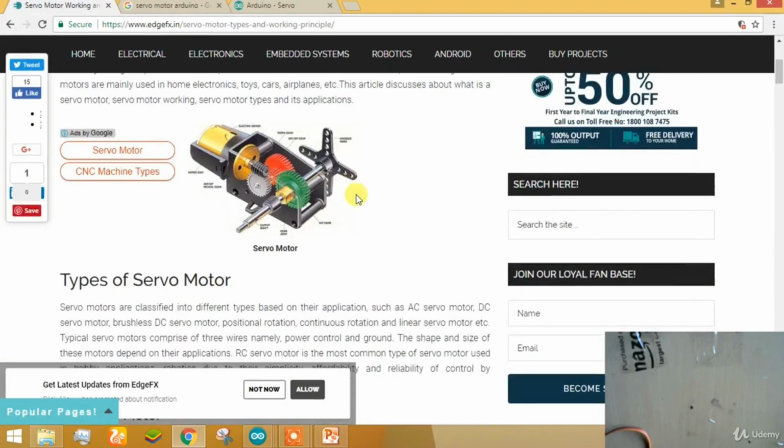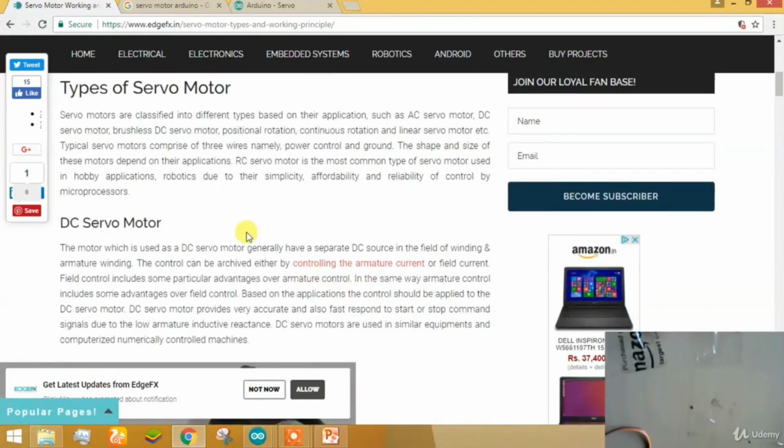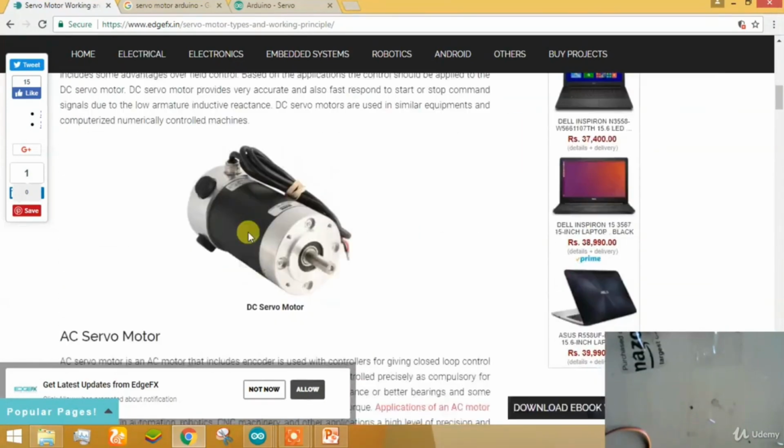This was the structure of the servo motor that we have talked about here. It is using a simple motor, and there are some electronics behind it with a potentiometer, and these are the gear trains. The potentiometer is connected which gives the value at which the servo has to stop, or at which the servo has to reach. The value correction is being done by the comparator which is pre-built in the servo motor, and the value for the signal input is taken with the help of Arduino, so that the Arduino can command the servo motor to get to a specific degree.